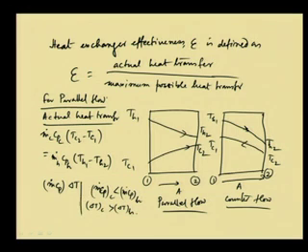Okay. So, this will be understandable because this is to maintain this. Therefore, the maximum possible heat transfer would be, suppose the cold fluid is among these two, whichever one is having minimum m dot Cp, that is called the minimum fluid. Minimum fluid means it has got minimum m dot into Cp with respect to the other one. If that is the minimum fluid, then it will undergo maximum temperature difference.